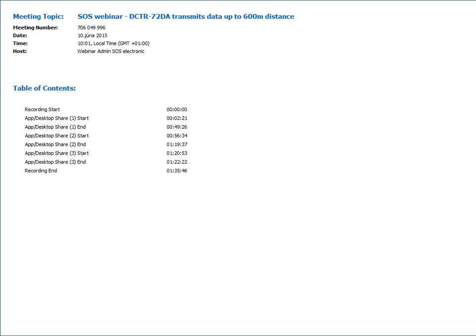Also, this handshaking and so on. We are using handshaking and this kind of thing. If you have direct communication, like the bridge, this is something you would have to program yourself. What we have for the DPA is basically the protocol for mesh networking. So you have 10 devices in the network. You can connect them from the UART, and you can send messages, even broadcast or one-to-one, to the UART or read from the UART. But creating a UART bridge is, I think, not a typical application of the IQRF, though it could be used for it.